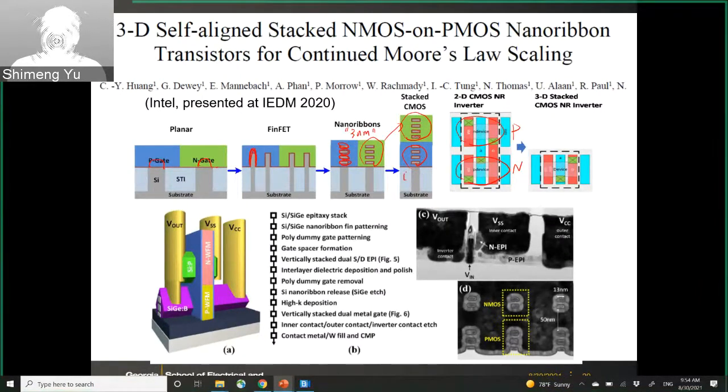Oh, you mean here? Yeah, what are those? Those are so-called STI. It's a shallow junction like isolation. Shallow trench isolation, actually. Shallow trench isolation is oxide, so it's to separate different regions. Like NMOS and PMOS, you use STI to separate the N and P.